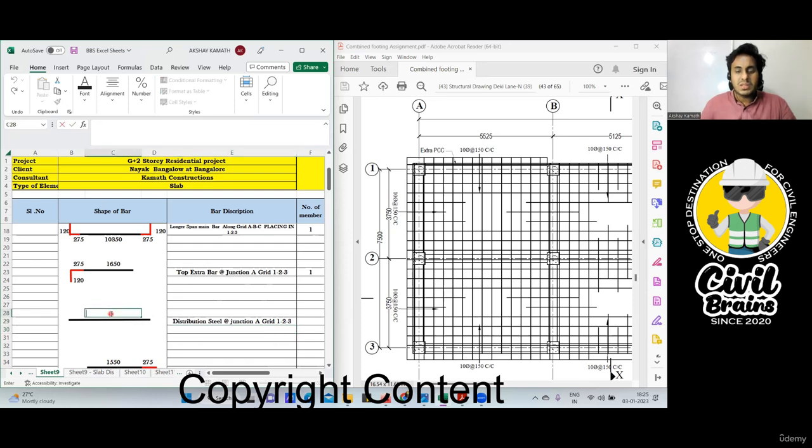This length how we'll find? So you'll come here, say plus. What is the center to center span? 7,500, no? So 7,500 minus half the beam from here. So 150 minus half the beam from here minus, what is this? Beam, no? 300 mm. I'll do minus. Finish. So this is a cutting length what I have. 6,900 is the actual cutting length what I require.